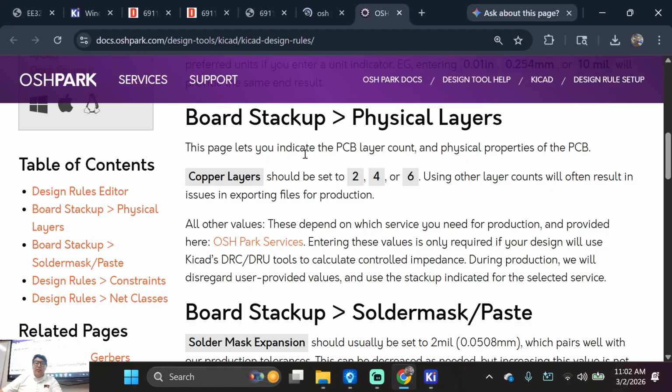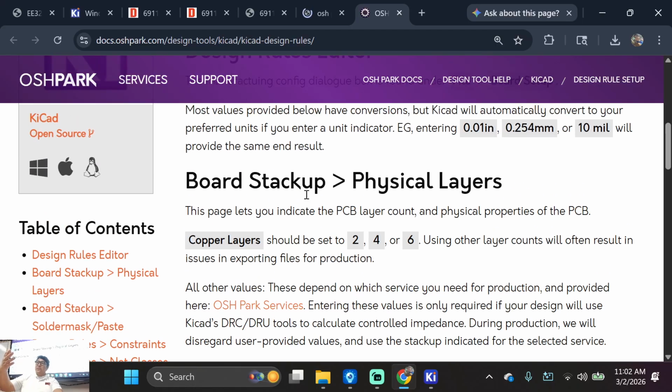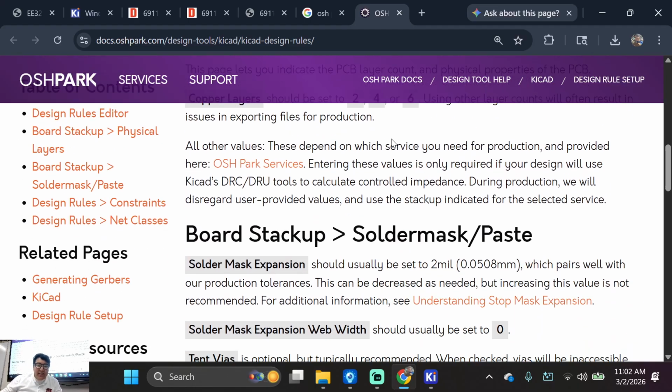Okay? This vendor can also do 4-level boards. So a 2-level board is top level and bottom level. You can solder on the top and the bottom. With 4-level boards, you think you can solder in the middle? Not really. You still have to solder on the top and the bottom. I think there's a fabrication that does the middle parts, some special person. But the point is, you can have 2-level, 4-level, and 6-level boards, but it gets more expensive, okay? We're just dealing with 2-level boards. If you're designing a senior design board and you want to make a 4-level board, it's going to be a little thick guy, really small but really thick, you be my guest, okay? So yeah, they can do that.